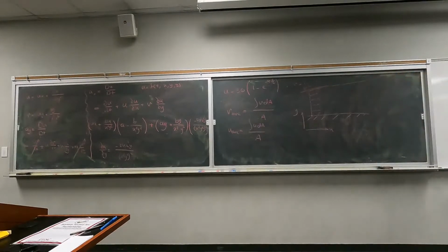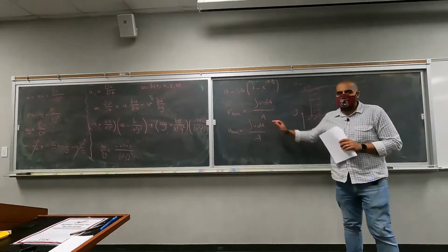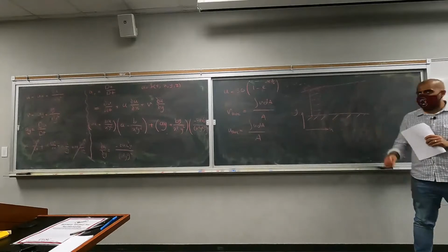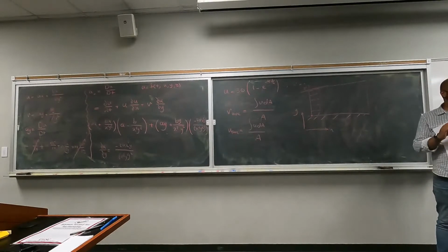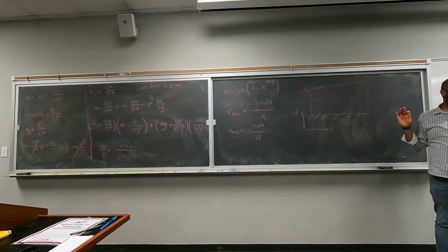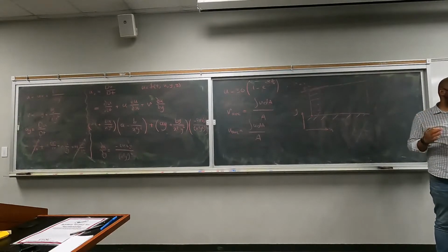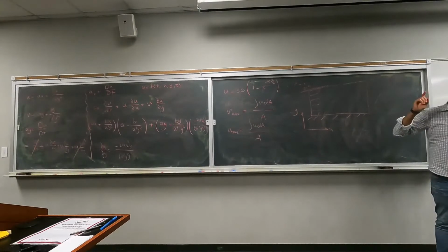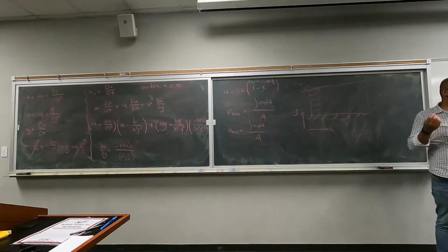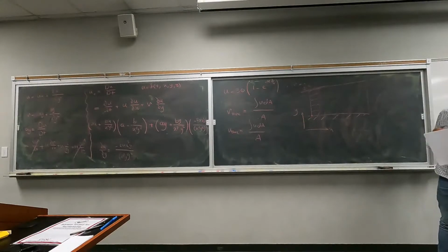And it's a one-dimensional flow. This area represents the cross-sectional area. How can we calculate the cross-sectional area? We are not given any information about the depth of this field, right? And it's a one-dimensional field. So it is safe to assume that the depth here is 1 unit, right? It can be 1 meter, 1 foot, 1 whatever, right? In this case, we are dealing with SI units, so it is 1 meter.